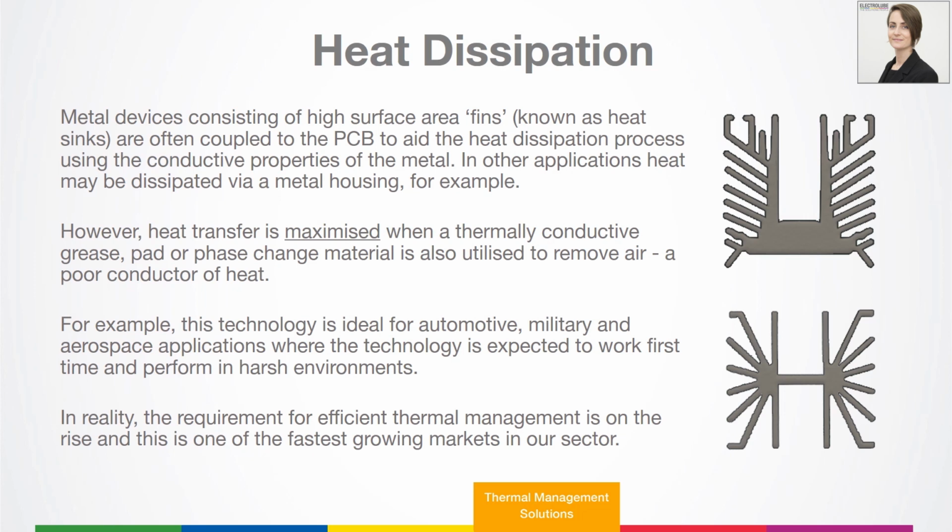heat. As a result, if you put a thermal interface material between them, something that is thermally conductive, like a grease or phase change material, for example, that eliminates all of the air from the interface and replaces it with something that is thermally conductive, that transfers the heat. This maximises heat dissipation and ensures that you're running at the lowest possible temperature for that device.